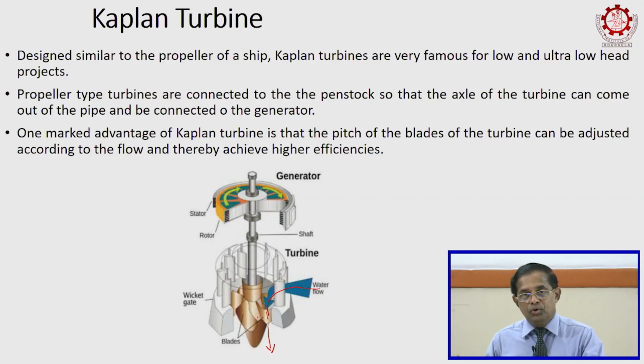Of course, we had one issue, as I told you earlier, that the penstock is FRP pipes, fiber reinforced plastic pipe. Because of vehicle movements, those got damaged by the pressure. So, we had to replace them. Other than that, about the Kaplan turbine, there have been no issues.